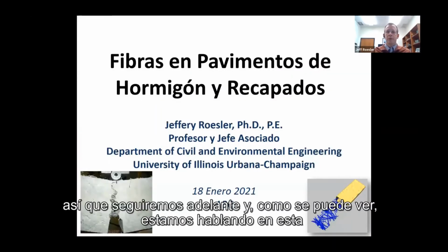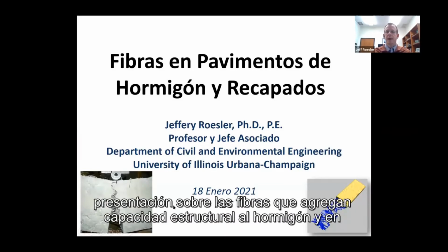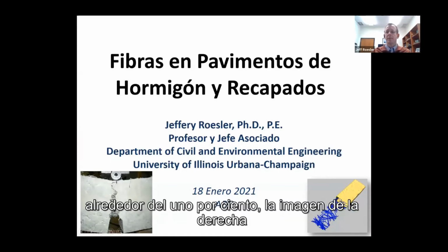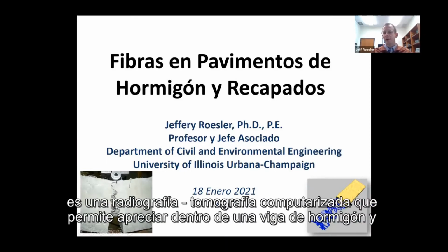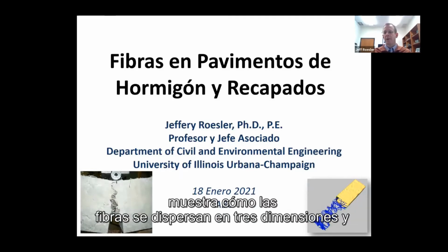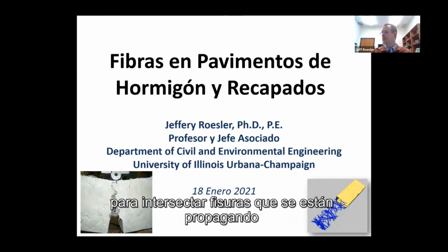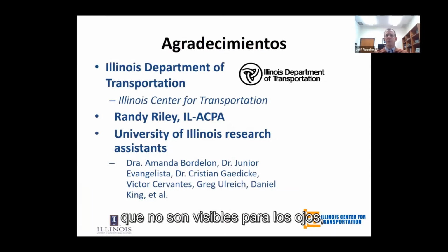So we will go ahead, and as you can see, we're talking in this presentation about fibers that add structural capacity to the concrete, and the picture on the bottom left is highly reinforced with fibers, about 1%. The picture on the right is an X-ray computed tomography looking inside of a concrete beam and showing how the fibers disperse in 3 dimensions. And this is how we enhance the cracking abilities, because of fibers' abilities to intersect cracks that are propagating that aren't visible to your eye.